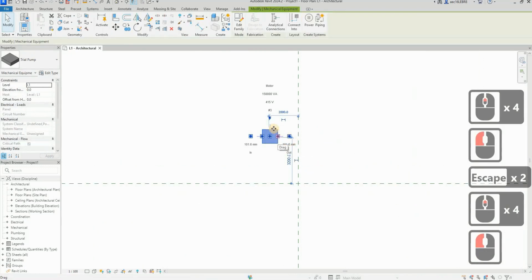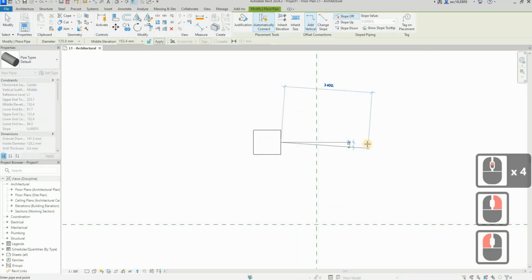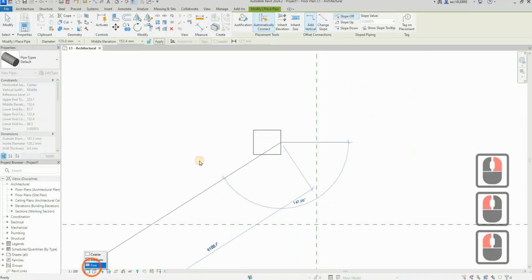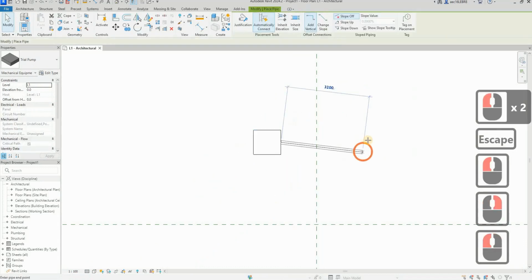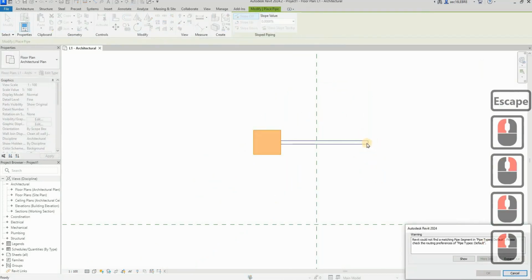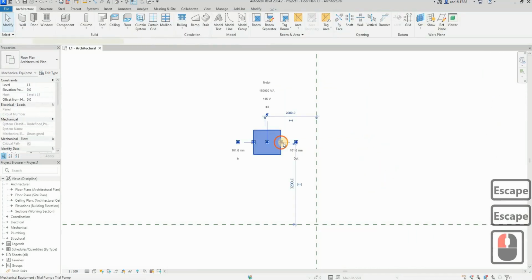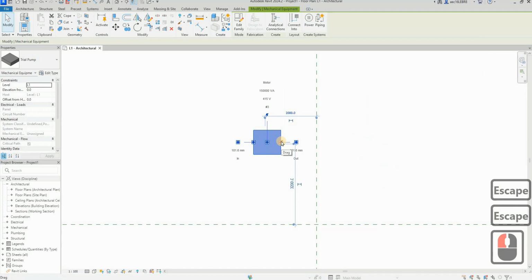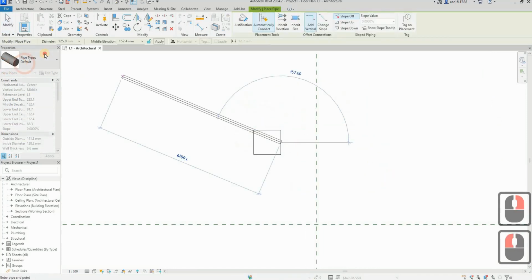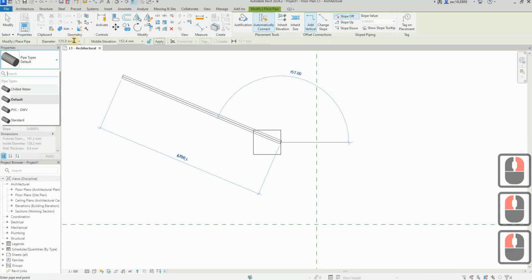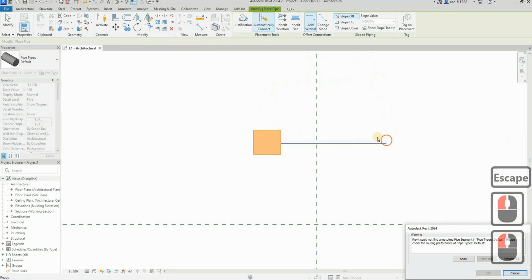So since you have connectors here, you can start to draw your pipes over here. Okay, change to fine. Then draw your pipes over here. So that's how you start to draw your pipe. Revit can't have matching sizes, of course. Then you need to draw pipe, but they don't have the size that matches your connectors.